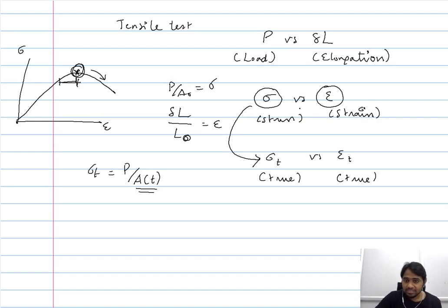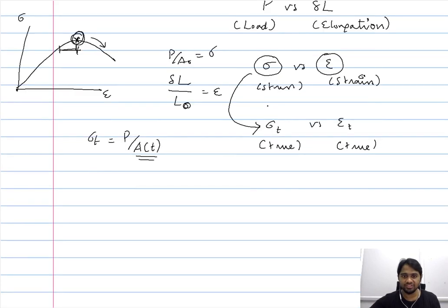Secondly, even though there is some ambiguity associated with this, now we are in a position to understand where this ambiguity comes from. And thirdly, to calculate the true stress and true strain directly, we need to have a sophisticated machine, so that increases the cost of testing. And finally, even though we arrive at the engineering stress strain curve from the testing machine, it is possible for us to convert that to true stress and true strain. So given all these reasons, conventionally when you talk about tensile testing, the result that you get is usually in the form of an engineering stress and engineering strain curve.